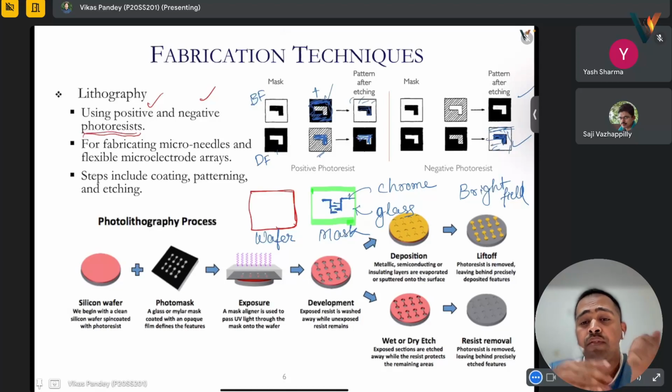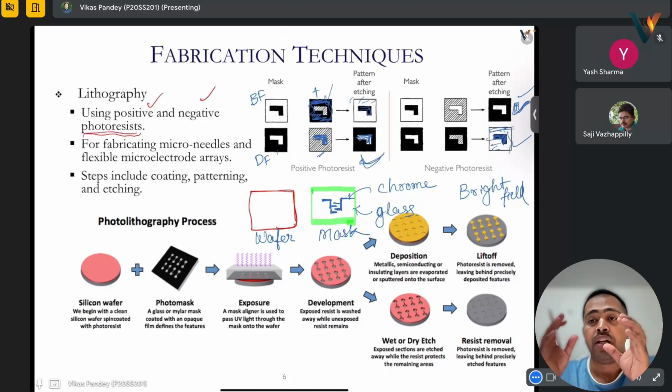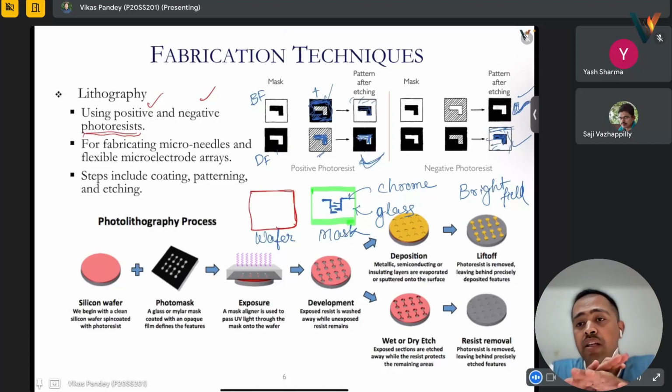Fine. There is one more technique. Some techniques use a dark field mask. What we were making from this dark field mask, right? The area that we want is open. Other areas are covered with photoresist. In this case, metal is deposited later on. We have this mask, we will take it, and then we will deposit using PVD techniques. Mostly CVD will not sustain. Not even thermal evaporation, it will be mostly suitable in case of sputtering and these techniques.